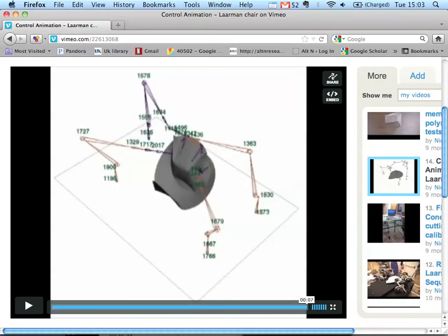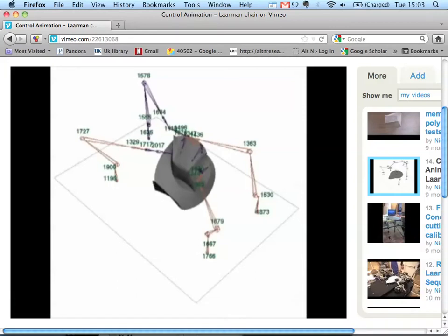Okay. So each one of those robots is calibrated into the digital one, knowing a minimum and a maximum. These joints are each solving it, right? So this is the problem: solve the joint. That joint's then linked to a servo, right? You have this much movement and it's been calibrated to be correct. Hit play, and the kinematics solve each axis.